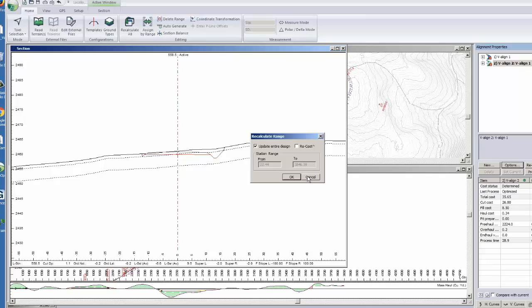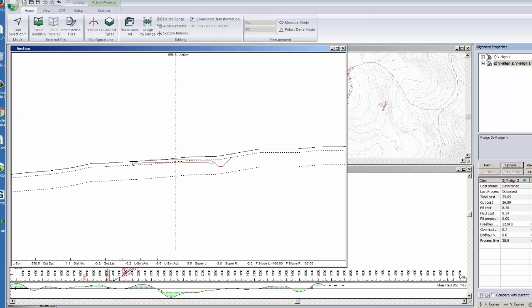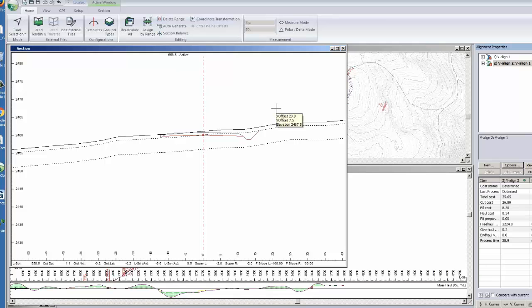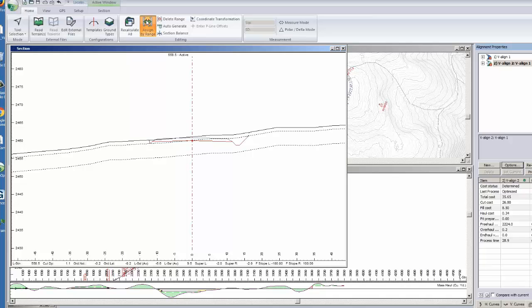If you've got some borehole information or geotech information, you can actually create a surface, a TIN surface, and use that surface instead of these depths. So back here, assign by range, go in here.